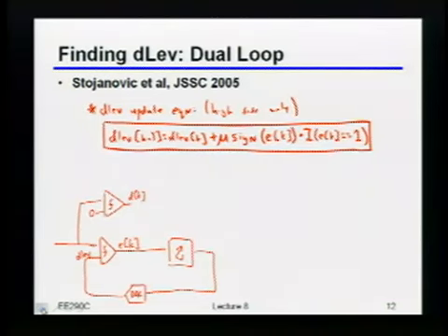Gate for 1 data bits. Yeah, so basically what I have to do is, only when I actually have a 1 data bit, and I'll just draw this conceptually for now, only then should I be updating the value of my accumulator. Because if there's a 1 data bit, then I know the level should be at the point where I'm trying to look for it. So only in that case should I update the loop to find this analog value.